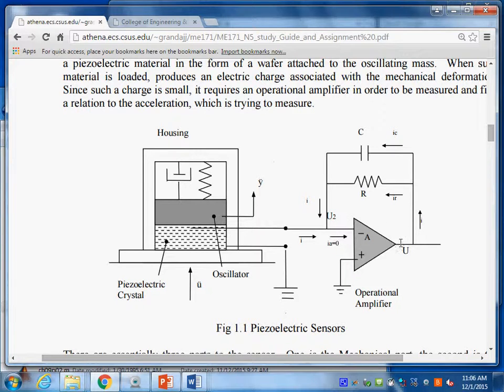But the device is deliberately designed not to draw current from the circuit, because that would be a little disaster. Instead of contributing to finding out the voltage, it would not make sense. The current has to be zero. So in this case, you have a voltage on this side, but you have an amplified voltage on this side. To be able to do this, we have in parallel to this operational amplifier a resistor and a capacitor.